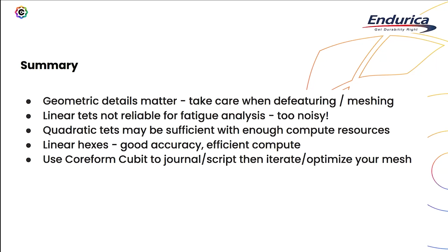And then once I've got a model where the contact is working and the material model is working and the boundary conditions are working, then I amp up the mesh. And this journaling scripting feature is really handy for doing that sort of thing.